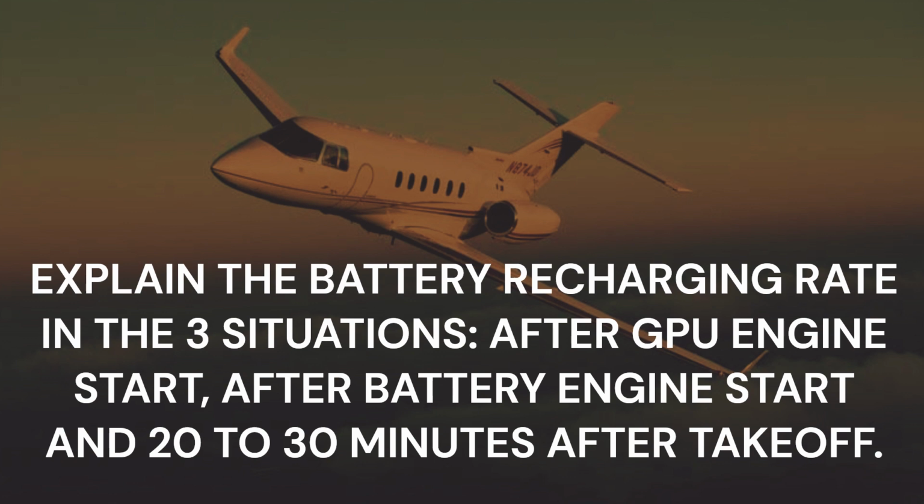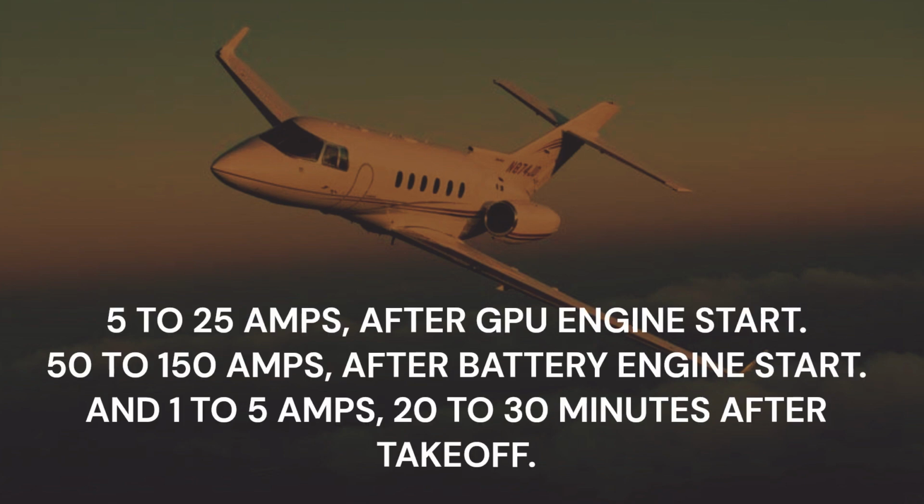Explain the battery recharging rate in the 3 situations: after GPU engine start, after battery engine start, and 20 to 30 minutes after takeoff. 5 to 25 amps after GPU engine start, 50 to 150 amps after battery engine start, and 1 to 5 amps, 20 to 30 minutes after takeoff.